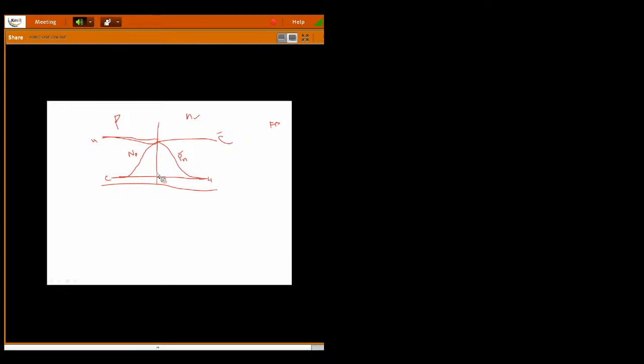Right. Now see at the junction, now this is your minority charge carrier. Now leave aside the majority charge carriers. This majority came here and became minority. Here also majority came here and became minority. Now in the forward bias, how is the concentration of your minority charge carriers? More minority charge carriers are there near the junction, on both sides. If I am telling about the P side, the same thing applies for the N side also.